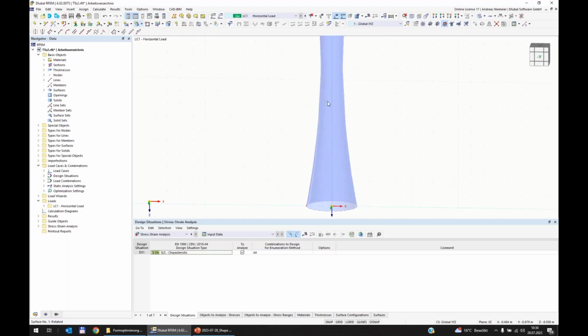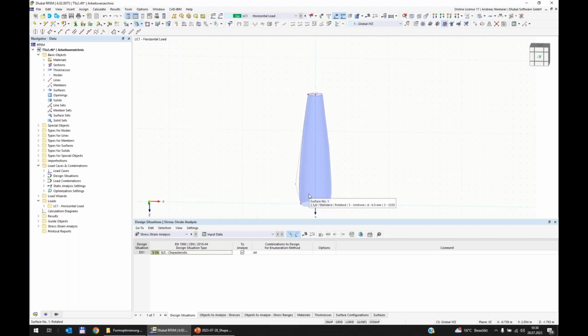Imagine now we optimize the place of the node according to our loading of the tower. Is it inside, outside? So we get a chance to model a structure which has a different distribution of stiffness over height. I use shell elements for this. But for me, it's important now that we have a new parameter.